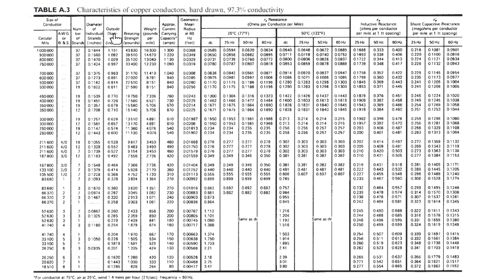So we have strands and we have the whole conductor, the outside diameter. And the breaking strength, weight, and current carrying capacity. So this is the capacity. You see now 1,300 for the conductor. We're talking about thousands for the conductor. So 1,000 is the capacity here. We're talking about 500 ampere or 600 ampere for one conductor.